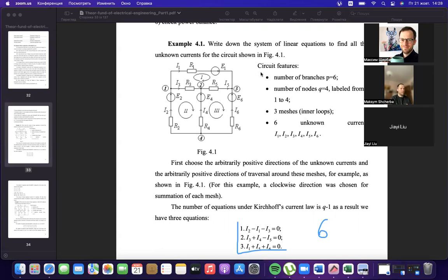The proposition is to make some imaginary variable, because the real current is the real current inside the branch. It is the current that we could measure using the ampere meter and the answer that we are searching for. But if we assume some imaginary value, called mesh current, that flows inside the mesh, inside all branches that are inside our mesh, and the same for each mesh, each with its own mesh current.